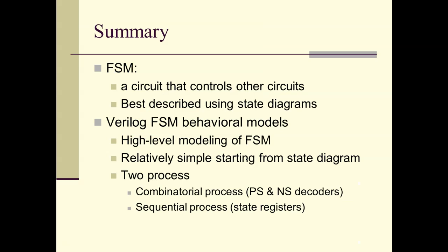So in summary, finite state machines are circuits that control other circuits. The best way to describe finite state machines is with a state diagram. The Verilog behavioral model is essentially a high-level way of modeling state diagrams. It's super simple, kind of cookbook, when you start from a state diagram. The way we're modeling it, once again, breaks the next state decoder and the output decoder into one combinatorial process, and also one sequential process that handles the state registers.